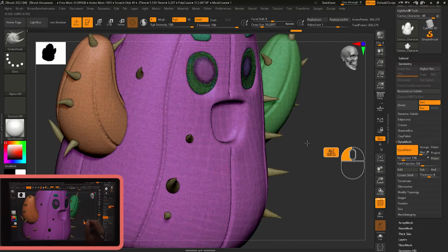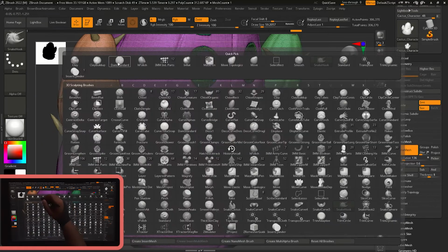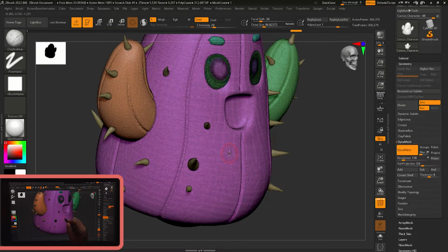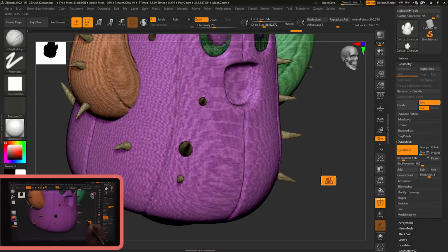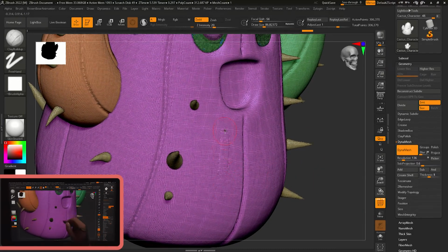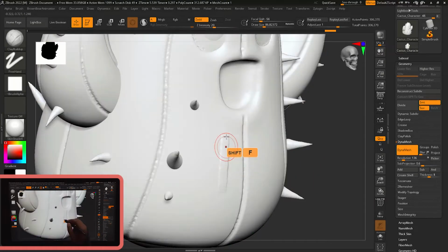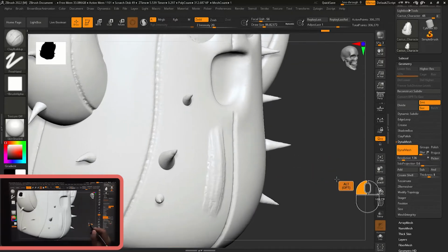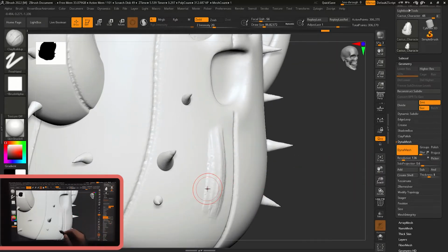If we are sculpting some detail on this mesh, I'm just telling you briefly about these things, but mostly we don't use all of these buttons. But yeah, you have to know what these buttons will do. So if we have applied some details onto this model, and we just reproject, like we just apply Dynamesh once again by holding Control, then if this Project button is on and the resolution slider is higher, then the Dynamesh will automatically get the details which I have sculpted over here.